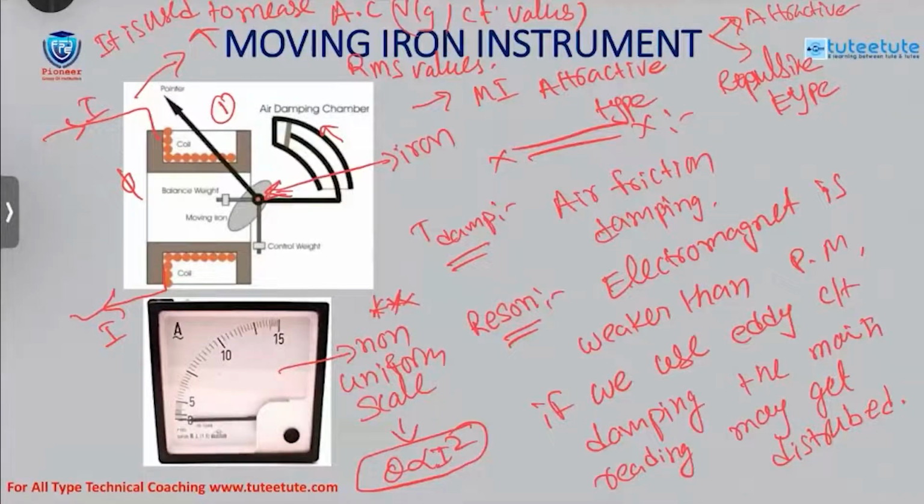But the problem is, compared to the moving coil instrument, moving iron instruments have some drawbacks, such as more power loss. We are going to discuss this in the coming session when we compare moving coil and moving iron. Just for now, remember the moving iron instrument can be used for both AC and DC measurements, but it is more efficient for AC than DC.